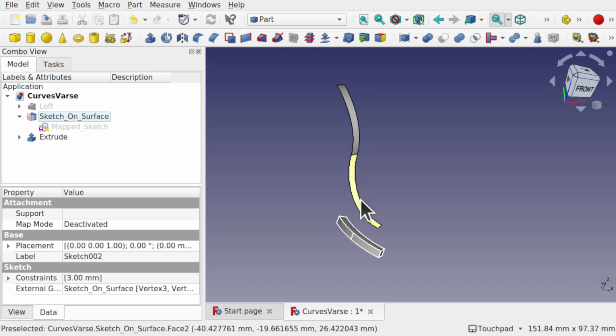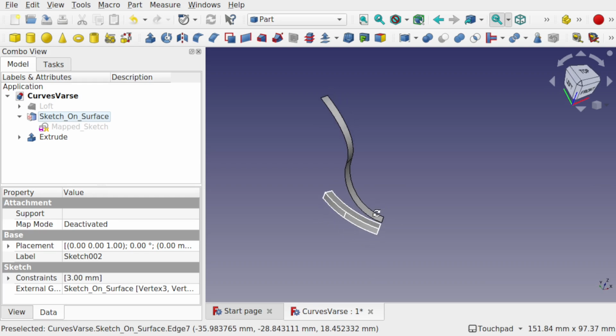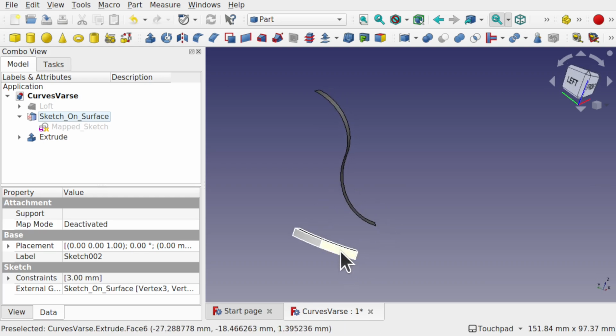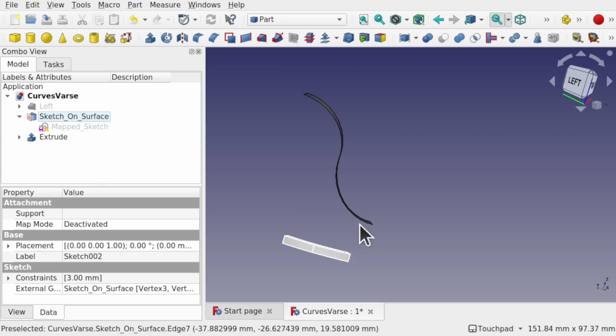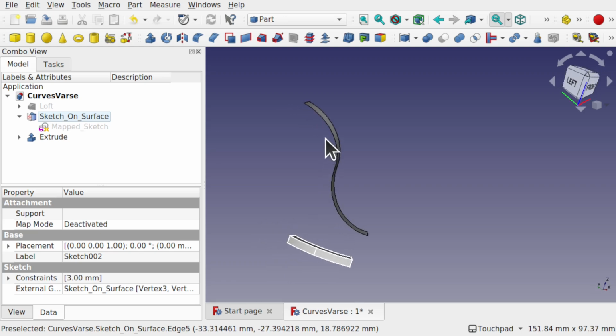We still need a face on this side because we've got a face and an edge, but we've only got one surface here. So we've got a surface and a solid. And I want to basically take this face, this edge, and connect it up with a face that will be here in this edge to make a curve between these two. So I need a way of creating thickness between here, and we're going to use a 3D offset for that.